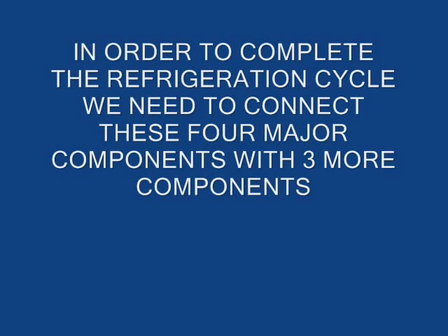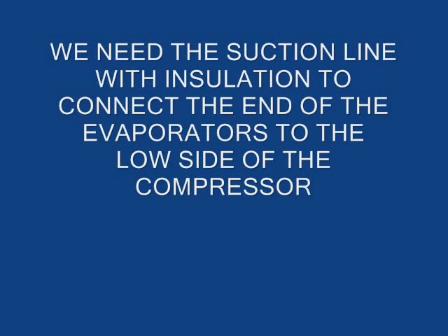In order to complete the refrigeration cycle, we need to connect these four major components with three more components. The additional three are: we need the suction line with insulation to connect the end of the evaporator to the low side of the compressor.